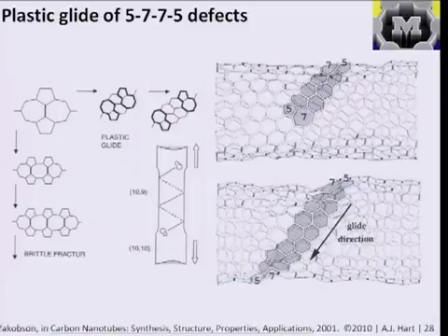And as these defects move, they stitch the nanotube down by 1 unit, basically taking 1 atom out of the lattice, and you can see the chirality in this model is going from 10, 10 to 10, 9. It's pretty certain based on this theory, which is maybe about 10 years old in the experimental sense, that this is the mechanism by which nanotubes decrease their diameter as they're elongated. You could imagine an analog to Poisson's ratio here, asking what the strain in the radial direction is versus the strain in the axial direction.